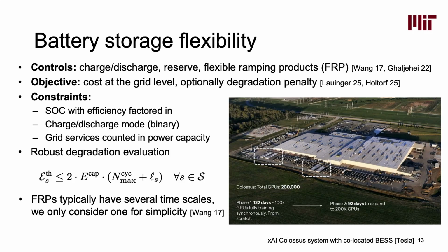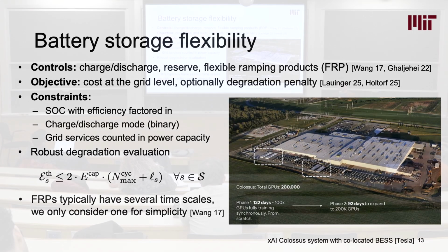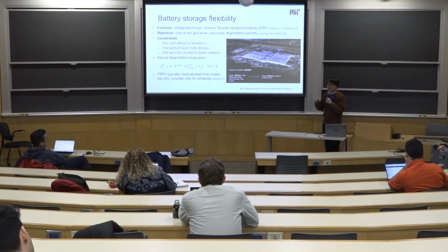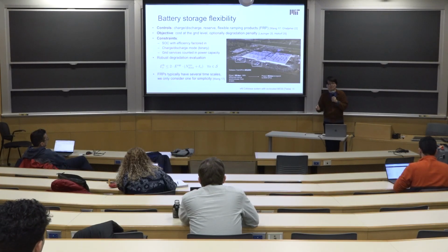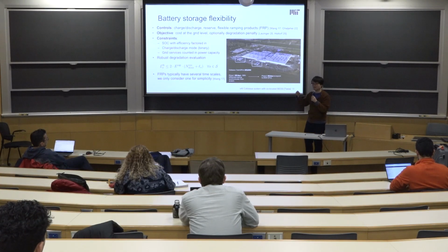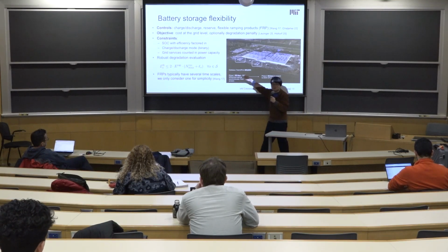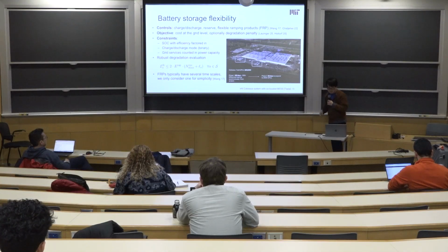But the battery is also not a free resource we can use. Batteries, just like servers, are expensive equipment. They have their own degradation risks as well. For example, Teslas these days say the maximum operation you can have is 150 cycles per year, which is roughly 0.5 cycles per day. And those could put some additional constraints on the battery operations as well.